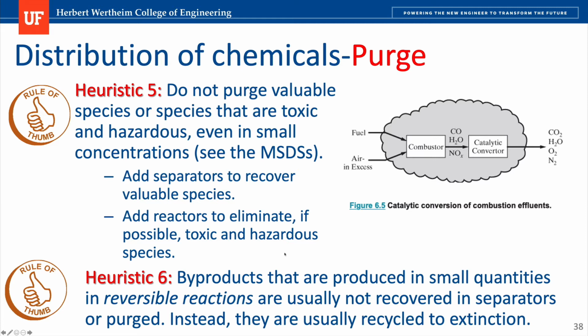Also think about that if you have something in the waste. First, before you call it a waste, you need to design something to mitigate those chemicals. Things like carbon dioxide, for example, in energy-based companies that produce energy, they have carbon dioxide in what is called the flue gas. And what they do is absorption methods using amines to remove and mitigate the CO2.